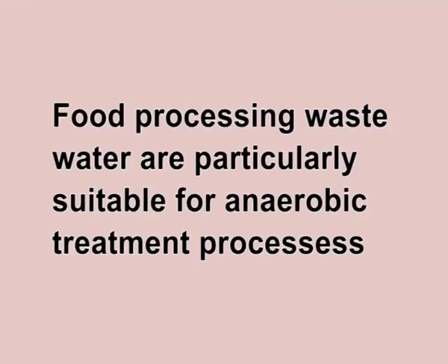Food processing wastewaters are particularly suitable for anaerobic processes. Firstly, because of their high organic load, and secondly because they rarely contain toxicants or inhibitory compounds. Indeed, excluding equipment cleaning operations for which chemicals and disinfectants are normally used, all the sources of wastewater are related to the preparation and processing of animal and vegetable derived raw material. The wastewater characteristics are therefore mainly dependent on the nature of the organic matter processed.